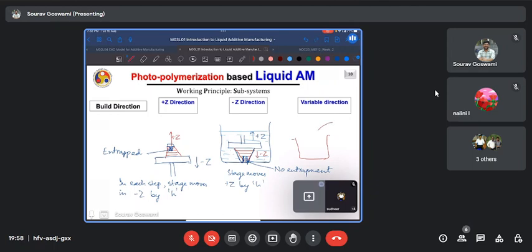Say you have an optic fiber that is delivering a laser attached to a suitable head, and this is flexible, and I can dip it in my vat, and depending on how I want the final printed part to be, I can move my deposition head freely such that it is always normal to whatever I am printing. And based on the movement of this flexible head, the final part I realize may be freeform.